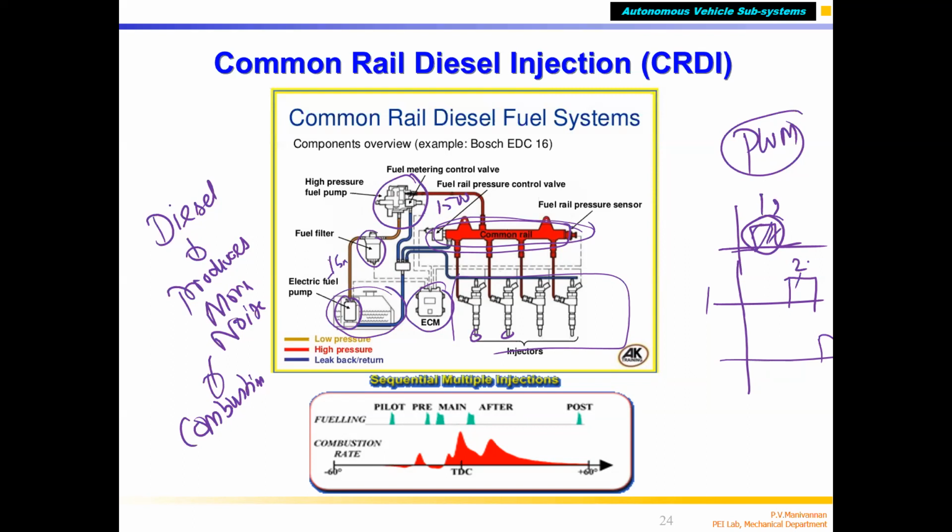That can be reduced if your droplet size is made smaller. If the diesel fuel droplet is small, that's why you're going to the CRDi engine. In a unit injector, the fuel injection is 300 bar, so droplet size is 100 micrometer. If you go to a CRDi engine, your injection pressure is 1,500 bar, and with a common rail there, pressure drop doesn't happen.